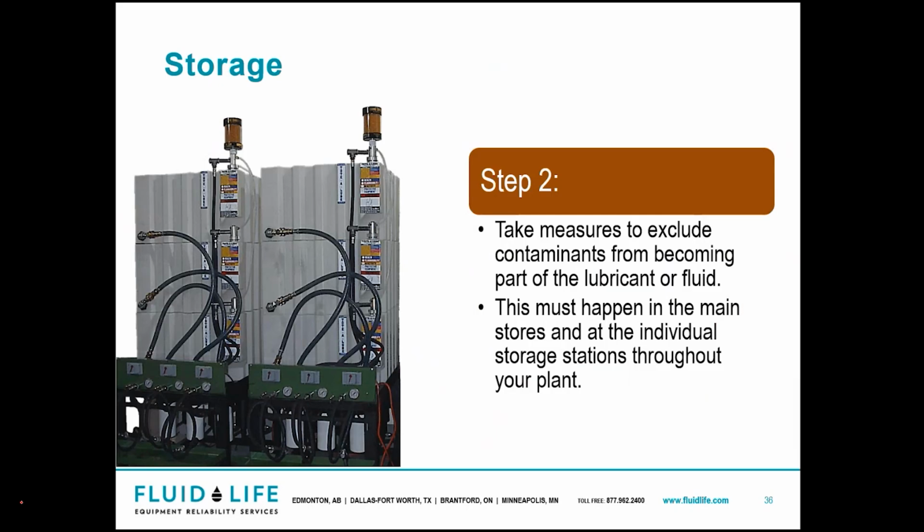Take measures to exclude contaminants from becoming part of the fluid. You've got to do this at the main stores and at every individual station throughout your plant. So your main stores have a nice setup like this, and even at your smaller sites, or your substations, even if you have something like a drum topper or just a drum pump that has a filter on it, something as simple as that will make a huge change.